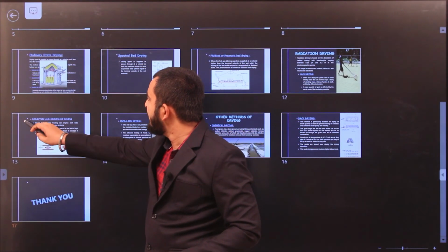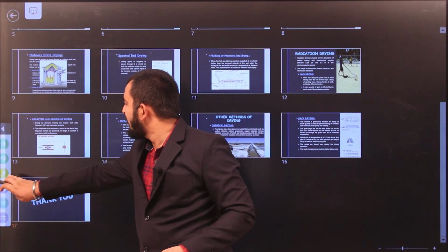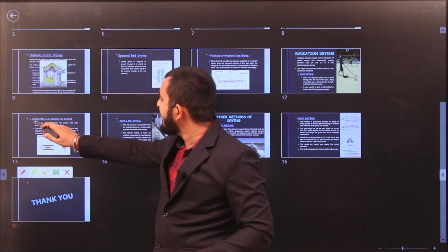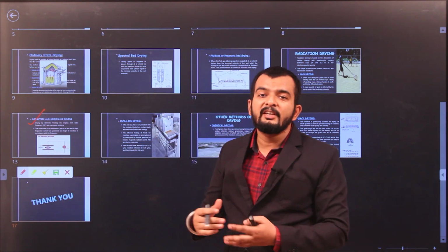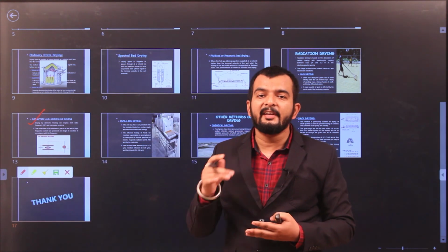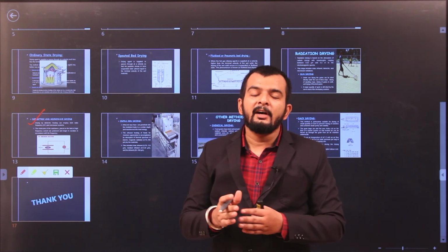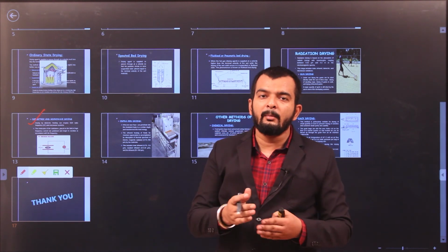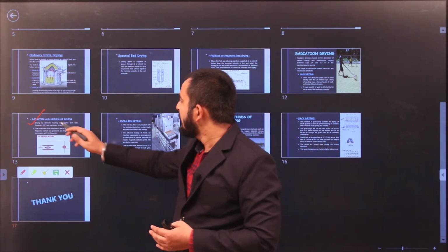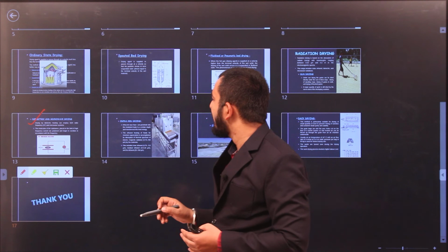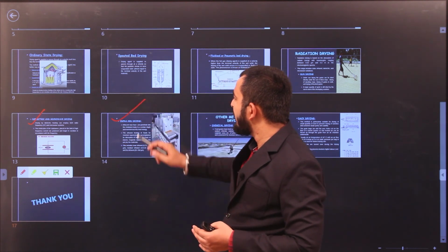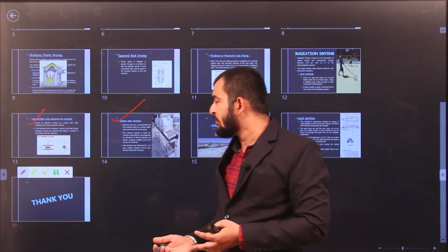Then we also studied dielectric or microwave drying. In dielectric drying, polarization of water molecules takes place and they oscillate at a very high velocity, and heat is generated through friction when the water molecules collide. We studied that in dielectric and microwave drying. Then infrared drying, direct heating through radiation.